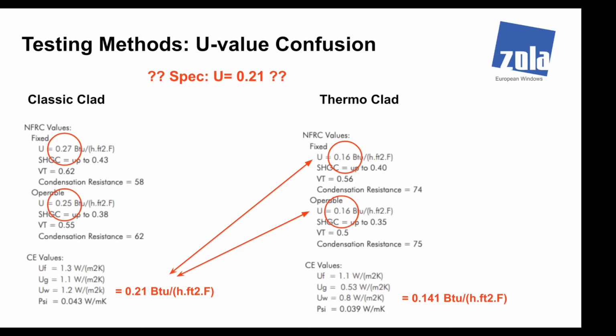So people are asking, you gave us a 0.5 glass, but I need a 0.38 glass. And I'm like, yes, this is actually a 0.38 glass when you convert it to NFRC and account for the blanking out of the frame, the opacity of the frame at that dimension.